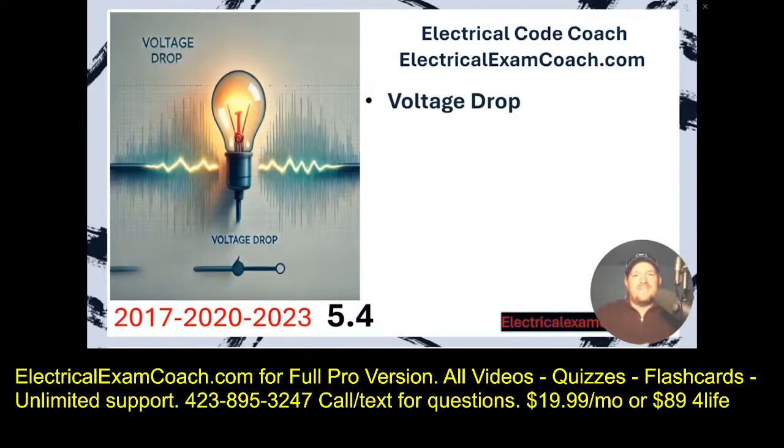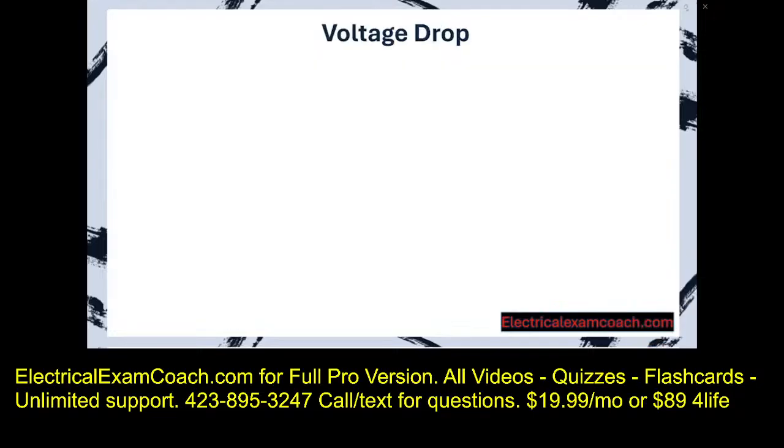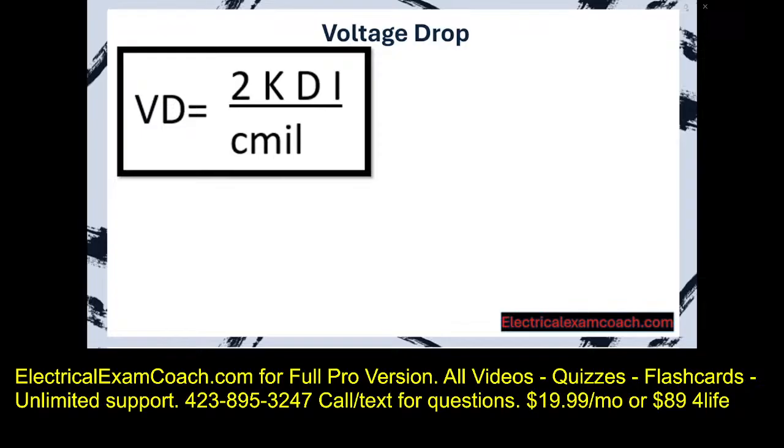Let's get to it. If you were to do an internet search for a voltage drop formula, you would likely find this one right here. Voltage drop equals 2 K D I over C mil. And that is an excellent formula. And it's actually the one that I use. But I've rearranged it so it's easier to remember.